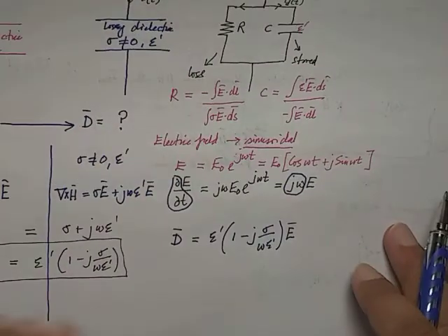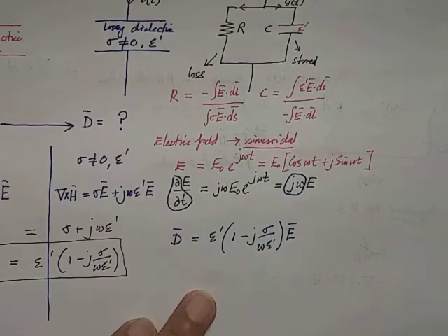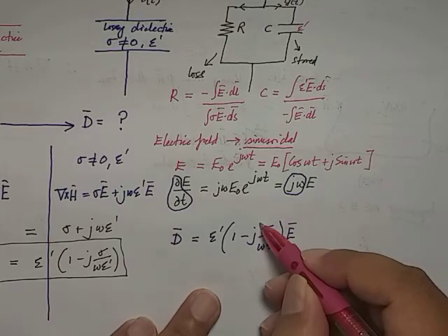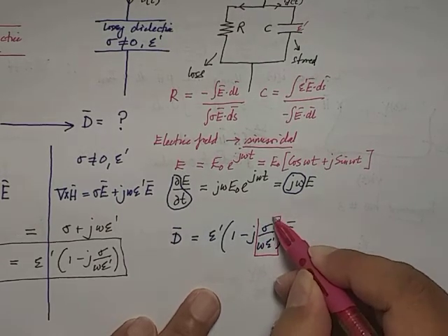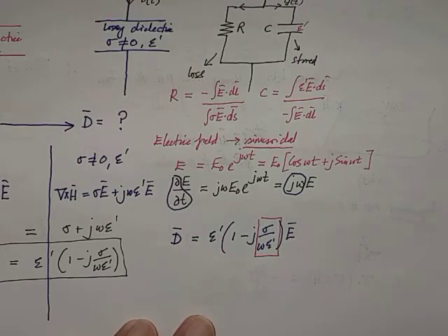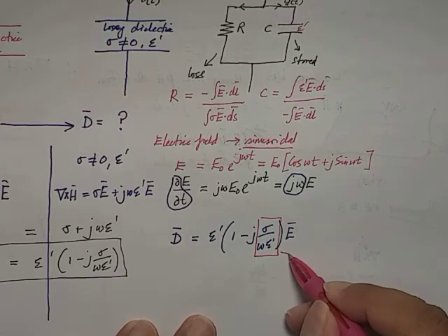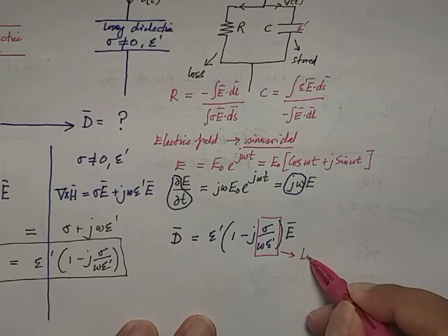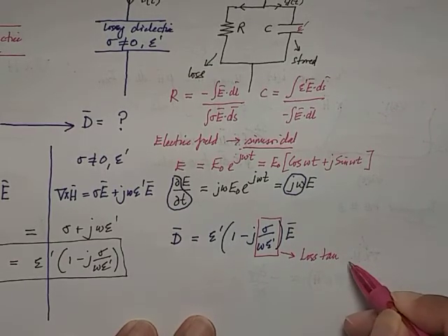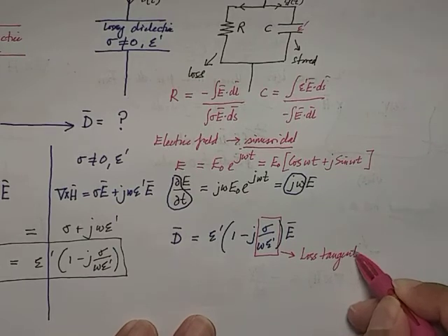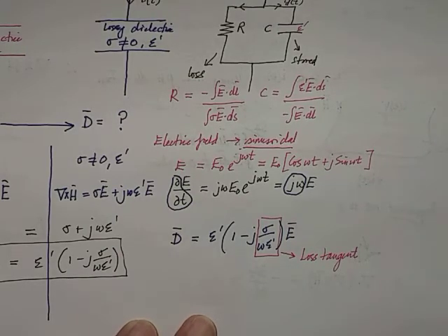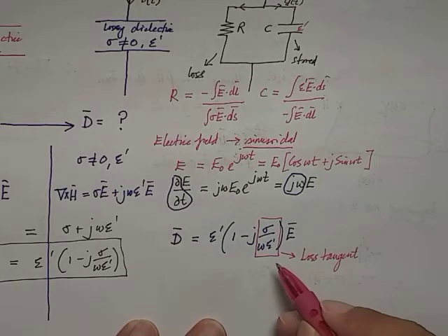Okay, extending further, when you see this equation, this term that we can observe here is very critical in the world of engineering, especially electrical world, and this term is known as loss tangent of the material. Yeah. So whenever we talk about material in future, this term is very, very important. I'm going to explain later on. So loss tangent is actually sigma over omega epsilon.